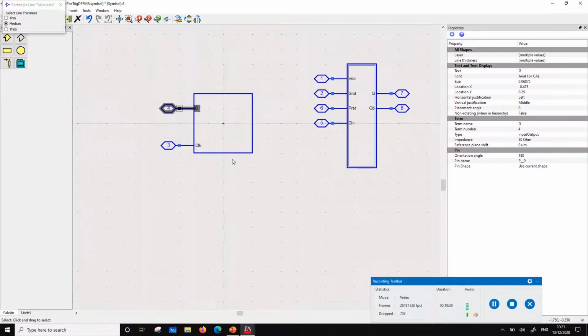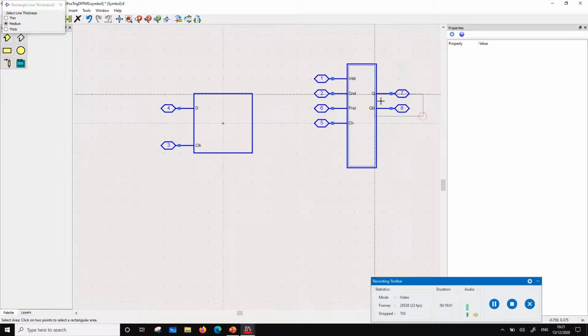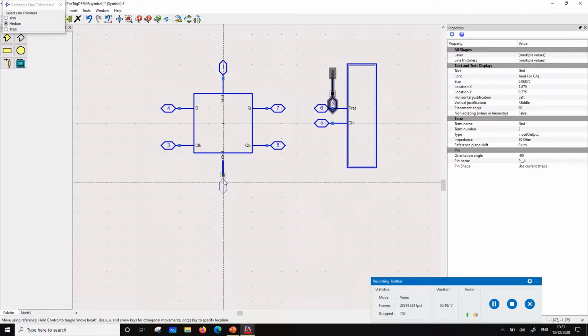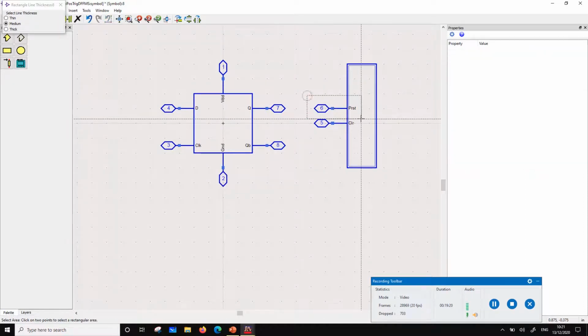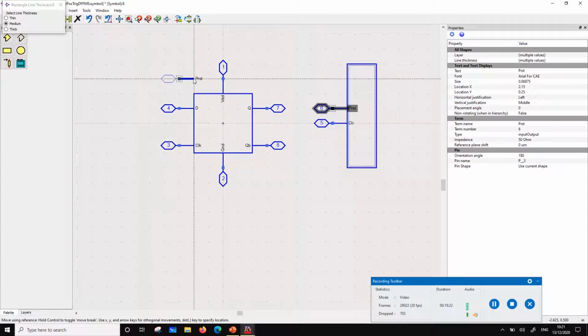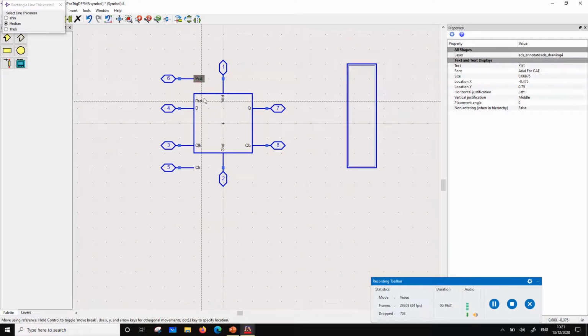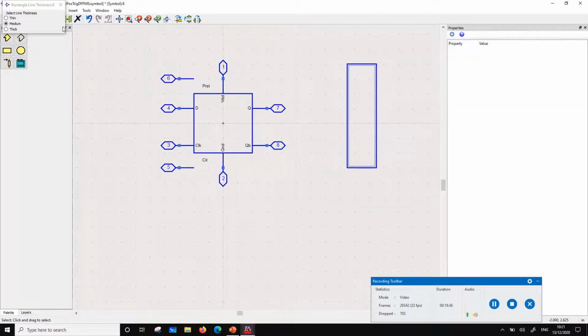This is going to be the D input, and this is Q and Q bar. This is going to be VDD. This is going to be ground. Okay, and I will do a preset over here, and I will do a clear over here, and I assume that is going to be preset bar, but I'm not going to change it till I verify this.